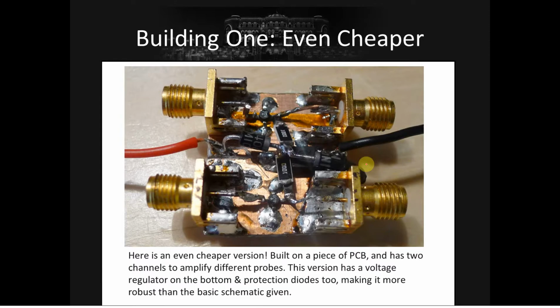So I have some of the parts there. I have the resistors, the inductors. The inductor is there. So these are the resistors. Power's coming in. I have a voltage regulator mounted on the bottom you can't see. And there's actually two of them here, which is a bad idea because you get cross-coupling. So what I don't show you is the shield that goes in between these two.